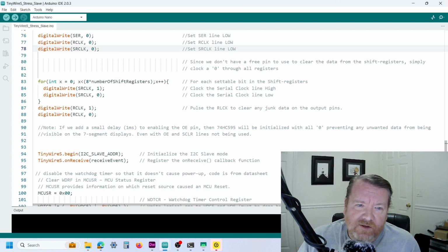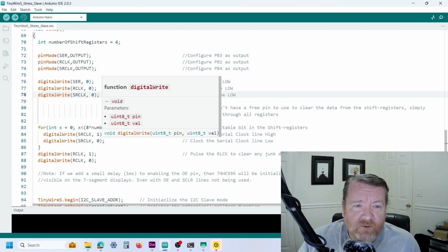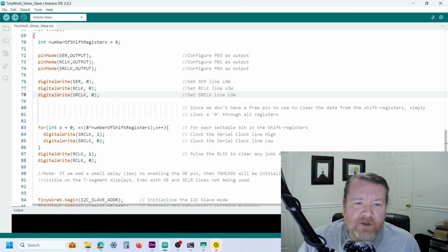And one trick that I'm going to do a bit later on is this is all done on purely the initialization period of this board. At no other time are we going to be needing to clear random data from the board. Each time we'll be writing new data and displaying it. So the only issue I have is on startup, and with a small little circuit I can actually delay the output enable pin. So if I can delay the output enable by, say, a millisecond, then this startup procedure will have been executed before the output enables. And as long as this is done before that enable pin is set, no junk data will be displayed, and I don't need to worry about touching the output enable or the clear line ever again.